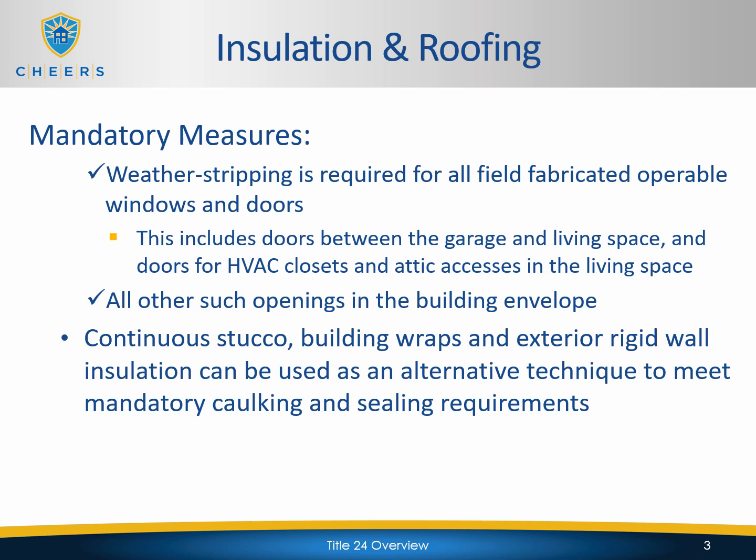Weather stripping is required for all field fabricated operable windows and doors. This does include doors between the garage and living space and doors for HVAC closets and attic accesses in the living space. All other such openings in the building envelope.